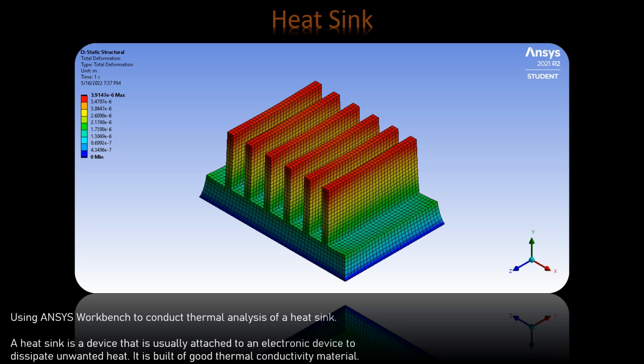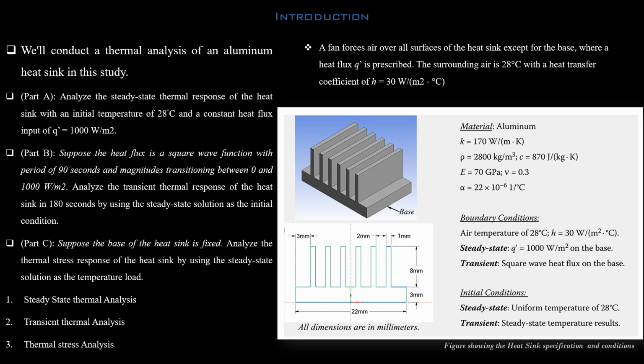Here we have an Ansys Workbench study to conduct a thermal analysis of a heatsink. We are going to conduct our study in three parts. Firstly, we'll do a steady state thermal analysis. Secondly, we'll do a transient thermal analysis. And thirdly, we'll conduct a thermal stress analysis.